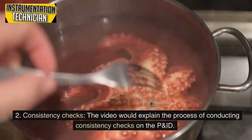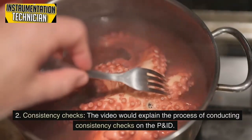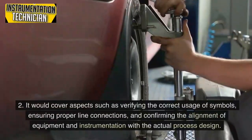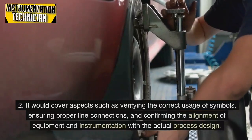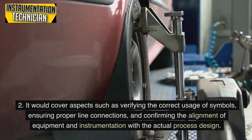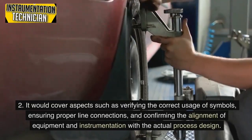2. Consistency checks. The video would explain the process of conducting consistency checks on the P&ID. It would cover aspects such as verifying the correct usage of symbols, ensuring proper line connections, and confirming the alignment of equipment and instrumentation with the actual process design.